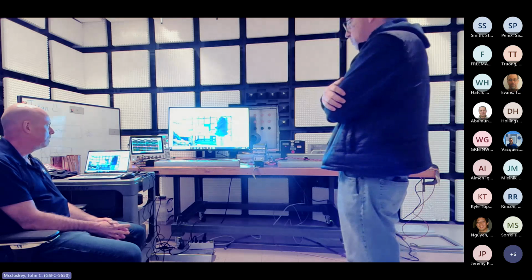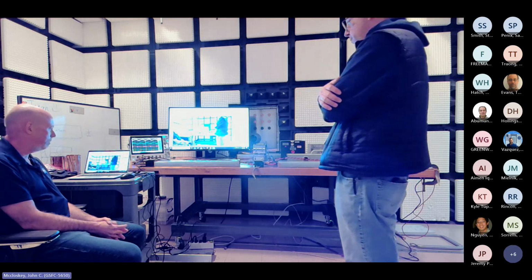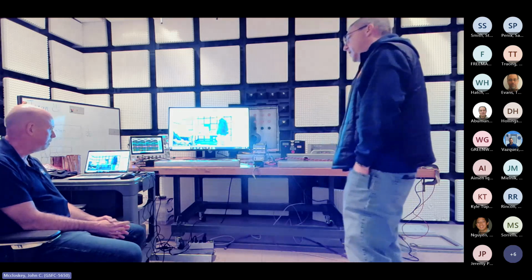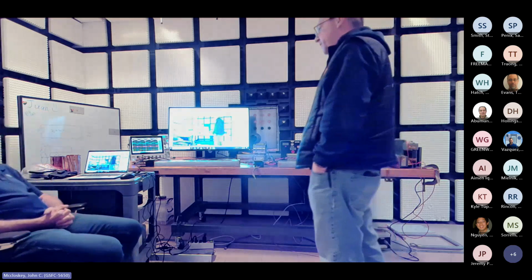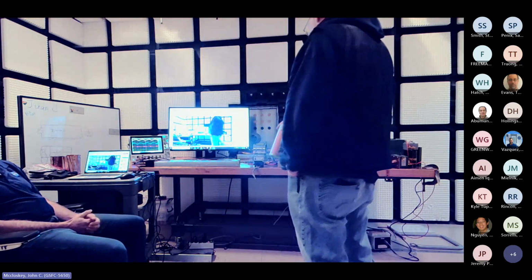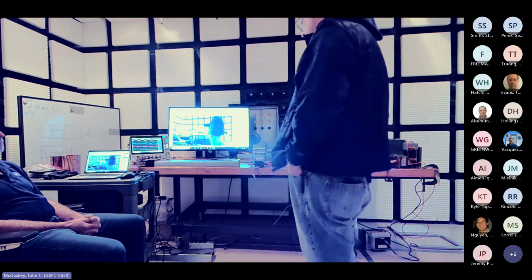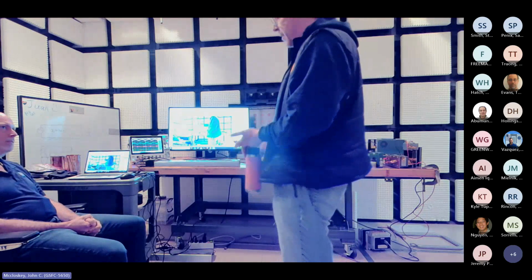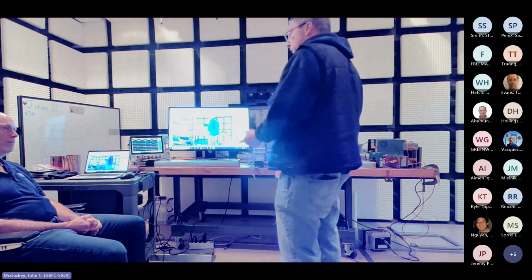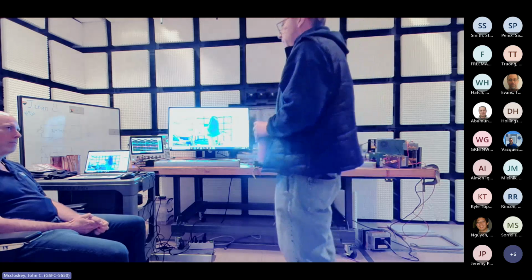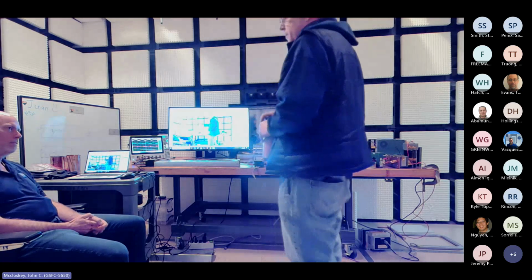You've been over here and we've used them here, Wayne. You can use a scope and do FFT aspects, but you really want to get that information for the scan you did. You're taking this measurement, now what's the probe characteristics? What's my cable characteristics? I have to take all that into account for my measurement, whereas if you have an FFT receiver in your software, all that is calculated. So you're immediately getting your answer.